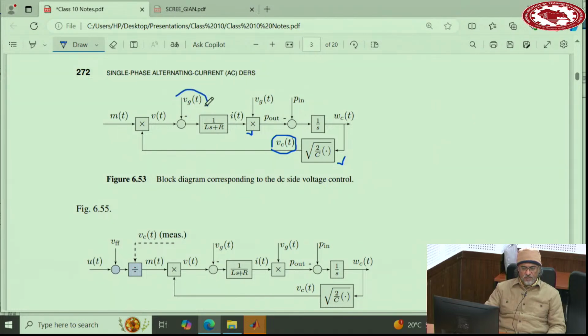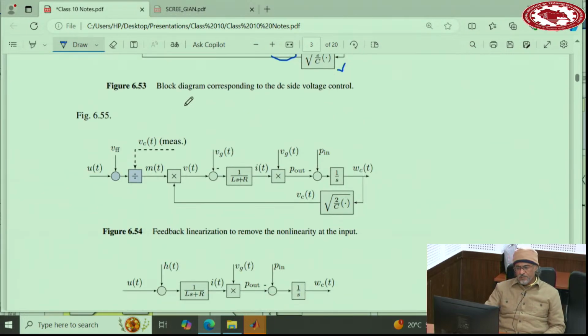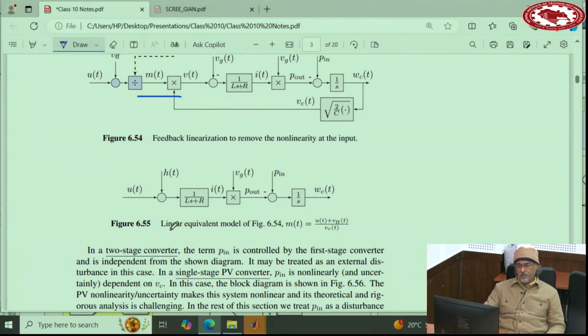And we are talking about AC systems. That feed-forward will be Vg passed through PLL and then coming here. If you apply these two, what happens is that these two cancel each other. Suddenly they go away, and this cancels each other. What remains? Only harmonics remain, because the fundamental cancels. PLL provides the fundamental component. So the block diagram simplifies a little bit to this diagram. So by using some initial feedback procedure, you can simplify the block diagram.